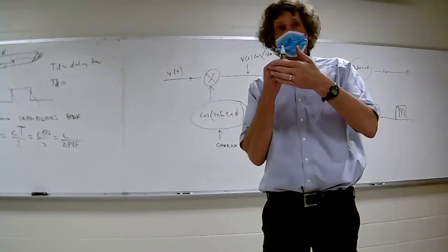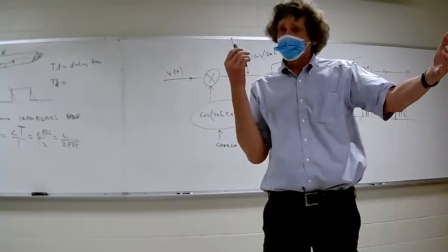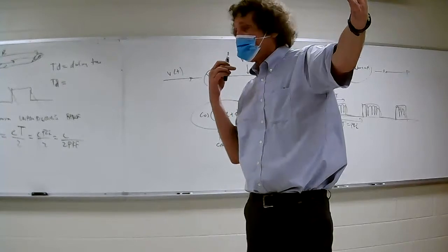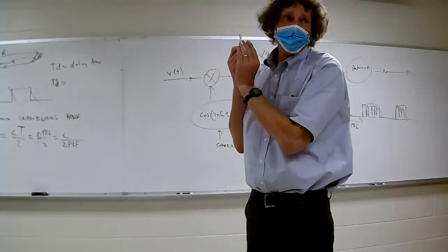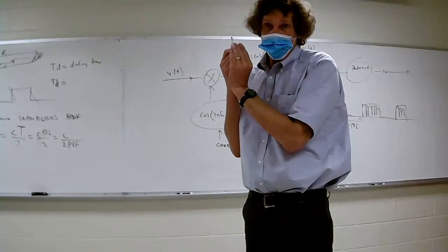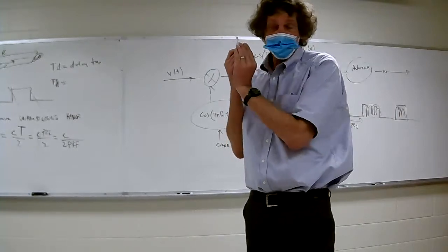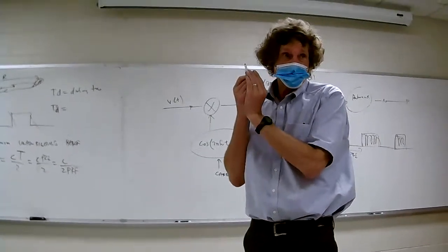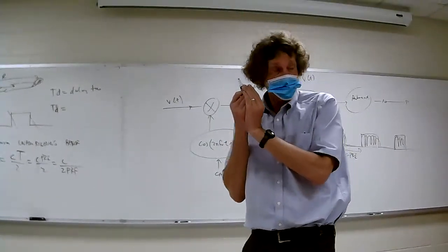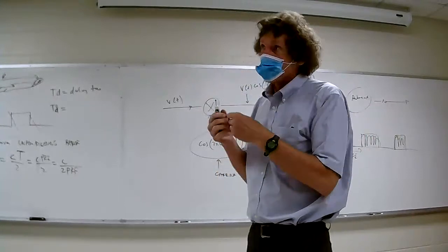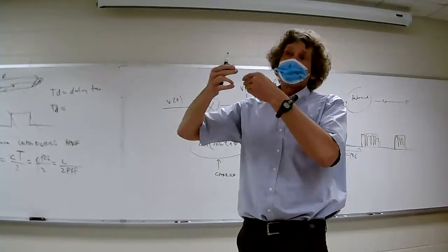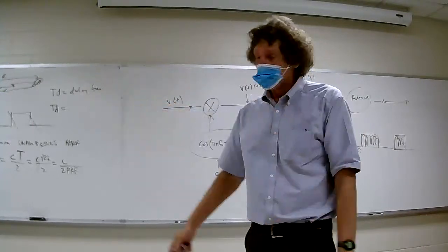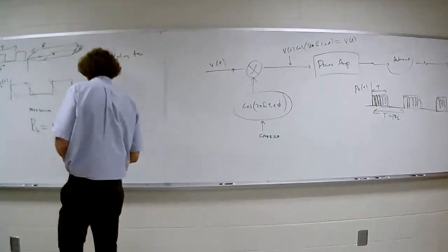Now, what they normally do is they say the largest possible target I'm ever going to run into is this big. I have to make sure that the return from this thing, no matter how far away it is, is so low that the signal is not going to really matter in terms of the actual analysis. So that's how they normally set the maximum non-ambiguous range for most targeting. Now there are other factors, but that's the general rule. You want to make sure you don't go so fast that near targets you won't be able to discern what range they're at. That's the maximum non-ambiguous range.